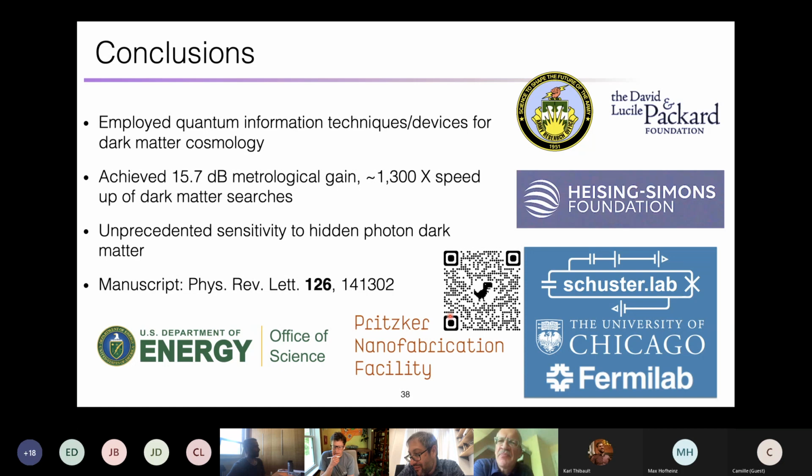Actually, the microwave photons can't get in. The reason we cover them with metal and we put it in a magnetically shielded box that's inside of another magnetically shielded box that's inside of another copper thing is because we don't want infrared photons. Even the next stage up is at like 100 millikelvin or even 700 millikelvin, and at that level you can get things above the gap of the aluminum, for example, and that can create quasi-particles.